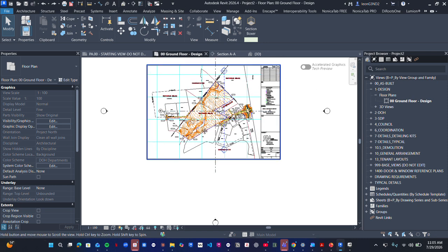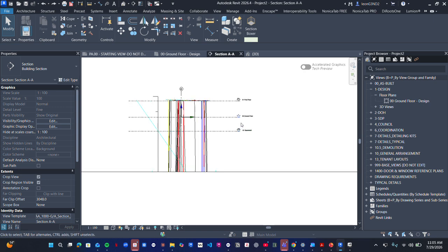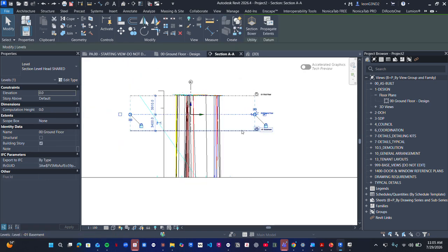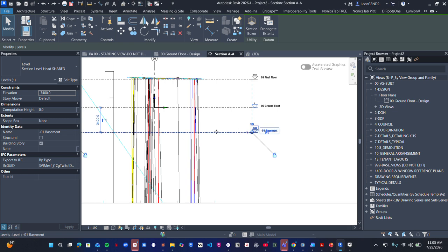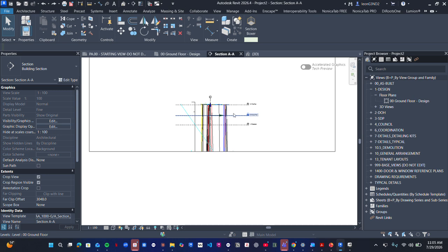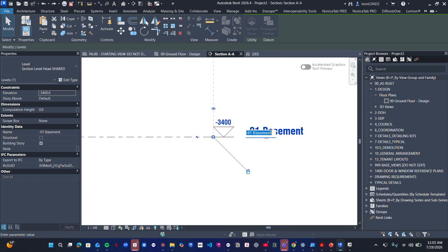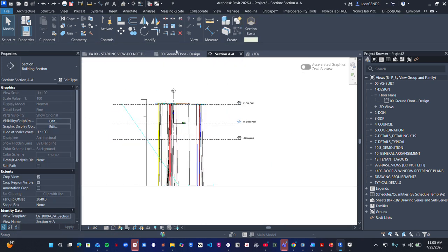So you can see here, another thing, like I said, that's good to keep in mind is the levels. These are the levels that you predetermine and use to start to build up your site, so to speak. You are able to change the name if you double click this. You can also add a level.